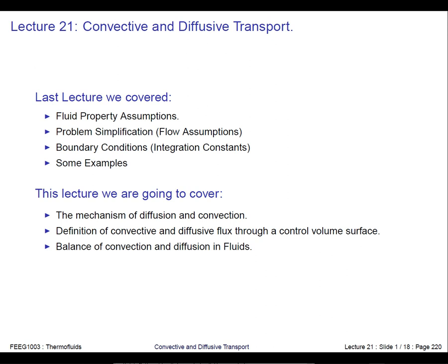And fluid mechanics is quite interesting because the relative strength of these convective and diffusive fluxes control the type of physics that we see. And we know about this already because we have diffusion and convection of momentum. And when the convective flux of momentum is much, much larger than the diffusive flux of momentum, the fluid is unstable and it goes turbulent. And this is represented by a large Reynolds number.